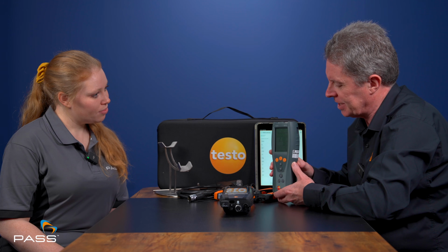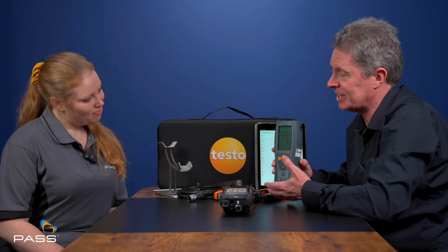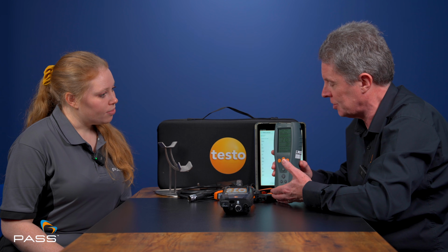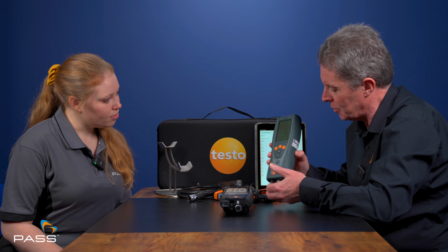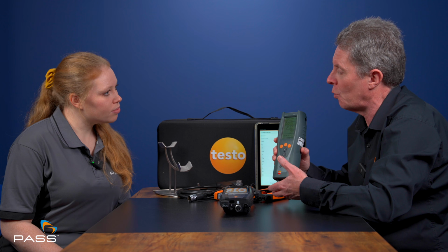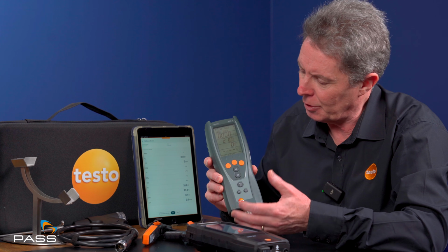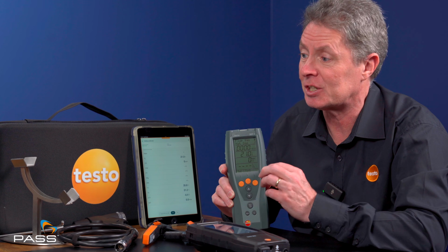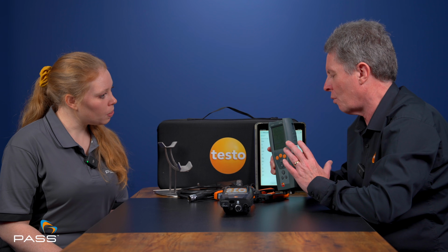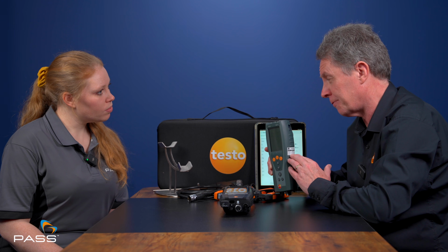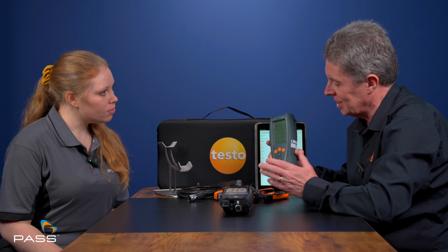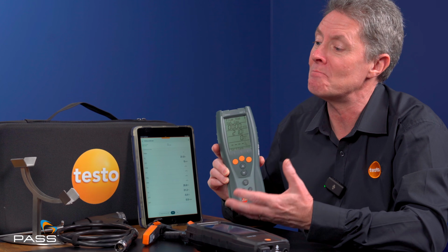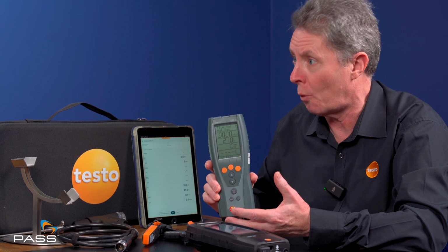This covers both the classic testing requirements for flue gas and combustion values, but with this, you can also use the accessory probes, for example, to do your flow and return temperatures. You can also do your tightness and let-by testing, so it's pressure testing on the device. If you're an engineer using, for example, solid fuels, you can do a draft measurement. So it's a flue gas analyzer and a multi-function device for general boiler engineers.